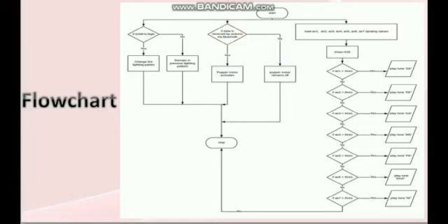The musical part has 7 LDRs which will be continuously reading 7 analog values, that is AV1, 2, 3 and so on, and we have set the threshold to 520. If the LDR is exposed to laser continuously, it will have a high analog value. If you interfere your hand in between, the analog value drops, and when the drop is below this threshold, a corresponding note is played. For example, if AV1 drops below the threshold, the corresponding note Sa from the sargam is played, and so on for AV2, AV3, AV4 and so on.